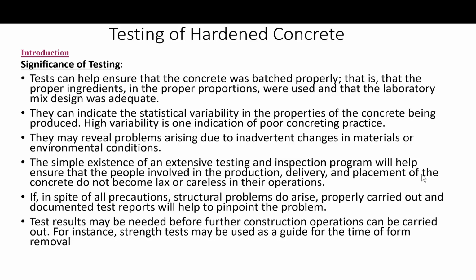Finally, test results may be needed before further construction operations can be carried out. For instance, strength tests may be used as a guide for the time of form removal or for the stressing of the pre-stressed concrete, pulling the post-tension cables, for example, something like that.